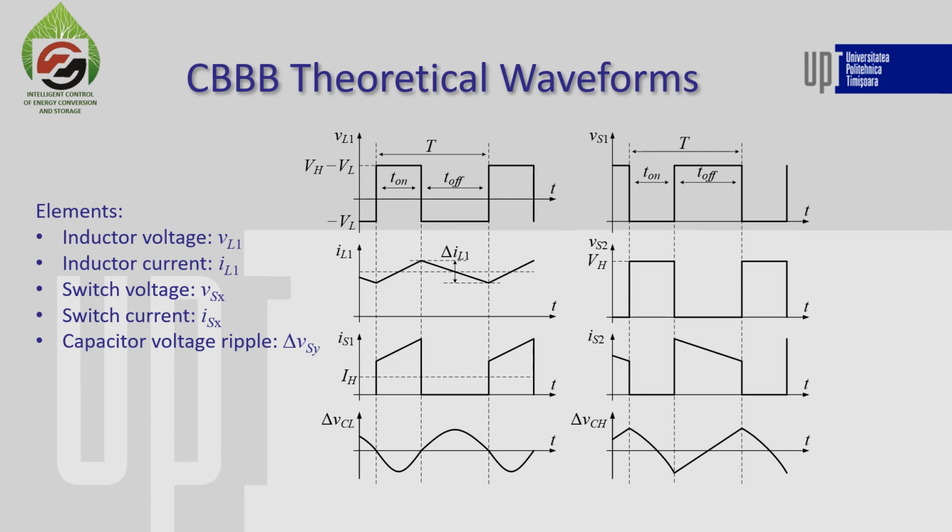Next, we represent the main theoretical waveforms. Here we have the inductor voltage and current, the switch voltages and the switch currents, and the capacitor ripple voltages, which are very useful when designing the capacitors.